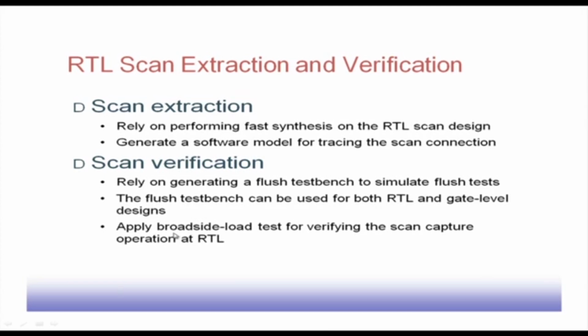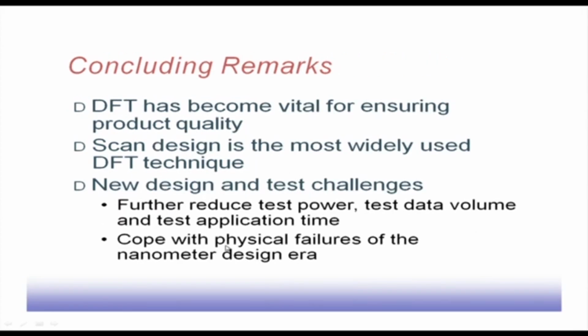Then we apply the broadside load test for verifying the scan capture operation. So, broadside load test is applying the test pattern and seeing whether it is getting the value properly or not. We will come back to this when we go to the detailed testing, this BIST testing and all that. So, for scan capture operation of the RTL, this can be applied.